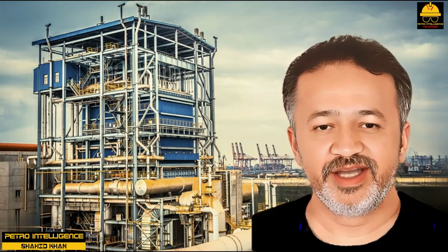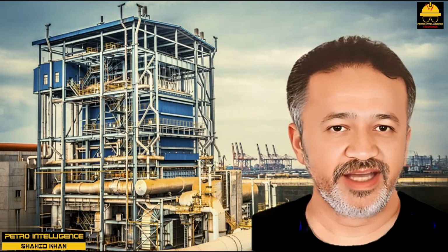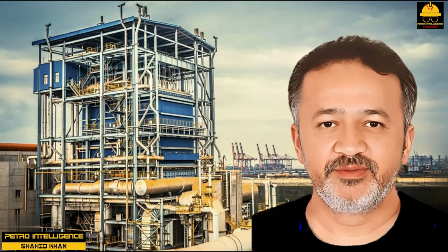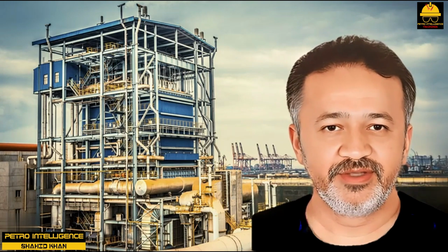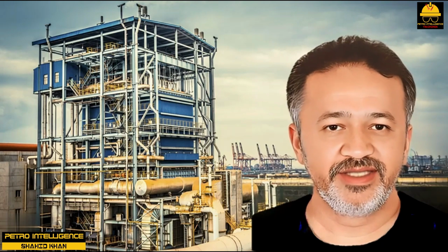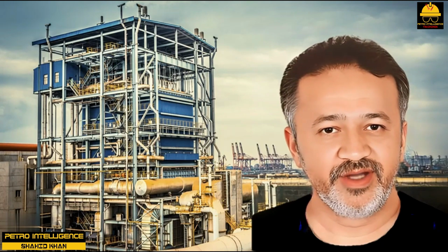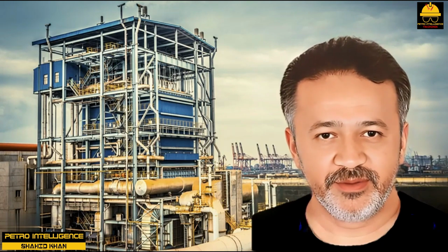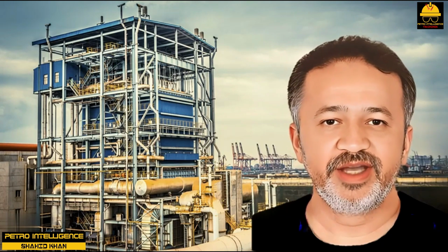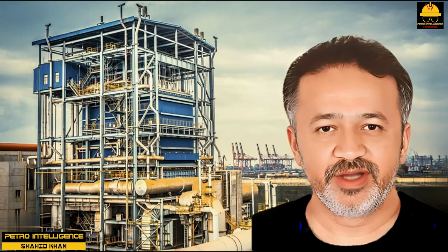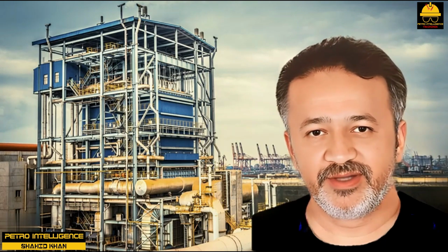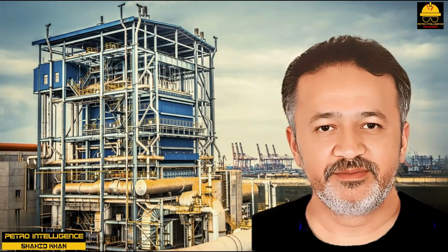apparently the end results are favorable, although we note that the life expectancy of the turbotal inserts may be a 2-year maximum, whereas spiral and fixable have up to 5 years service time. Naturally, these tube inserts may be attractive as retrofit items, with potential savings in energy costs and reduction of downtime for exchanger cleaning, but it is important to be careful when selecting these, as with any piece of equipment, to be sure that the tube inserts are appropriate for the service for which you intend to use them. Note that both spiral and fixable can withstand back flushing for cleaning, but turbotal cannot.